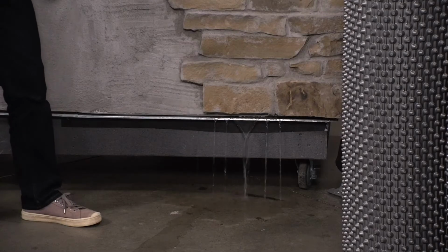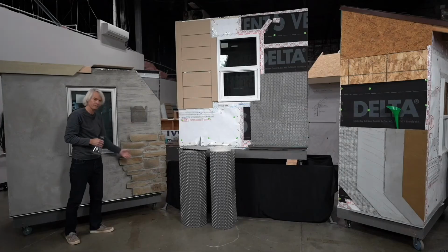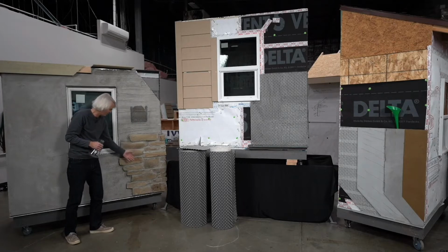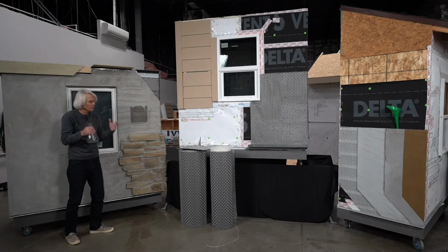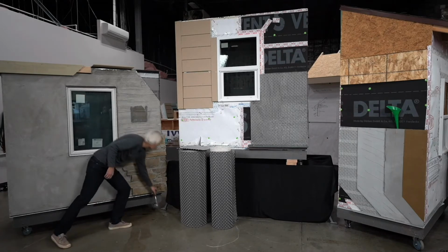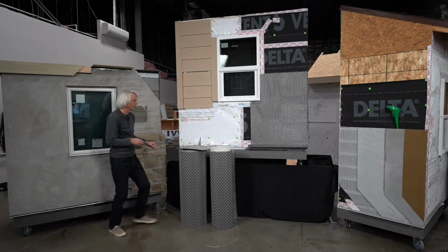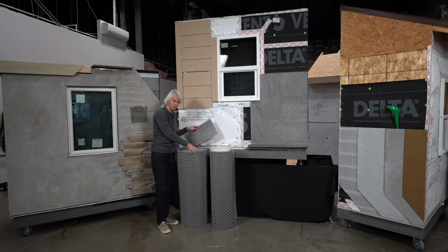So that's pretty darn remarkable. We've got rapid drainage and ventilation on the back, and very accelerated drainage on the front side. That is really cool to see when we talk about building durability, is getting rid of that water. That's what we want to do. We want to evacuate water. We don't want to store it on buildings, especially wood frame buildings. That's a critical thing when we talk about building durability. It's about water, control of the water, control of the water.